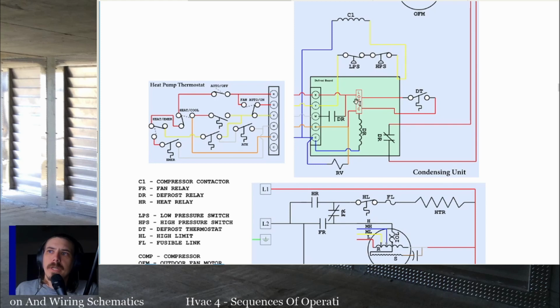W goes through a relay into the board because it will actually power W in defrost. O goes through the circuit board and then down to the reversing valve, and that has an extra power source to it so that the defrost board can power the reversing valve if necessary when initiating defrost, which is always necessary if you have an O terminal. If you have a B terminal, it would be the opposite. But this whole schematic is based on having an O terminal, not a B terminal. B terminals, of course, energize the reversing valve in heating, not in cooling.